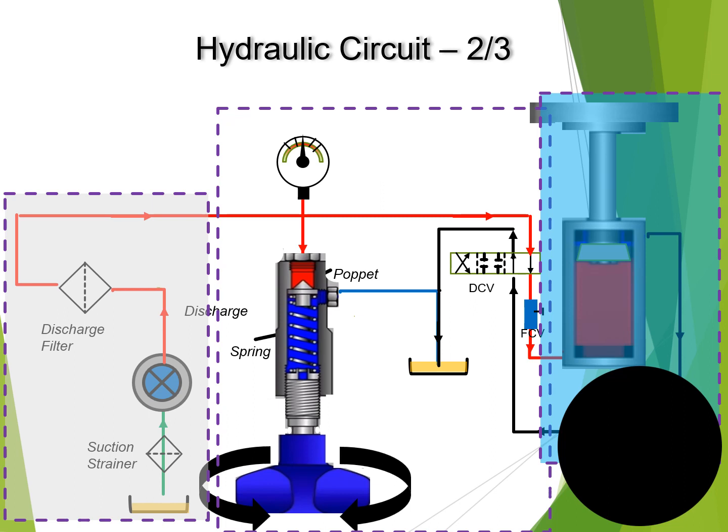On certain conditions, the direction control valve bypasses the actuators and sends the fluid directly to the sump. So if there is any problem where the actuator is not functioning, the pressure relief valve will pass the fluid, but the direction control valve will act here and will not allow the fluid to go to the actuator; it will rather send it to the sump.